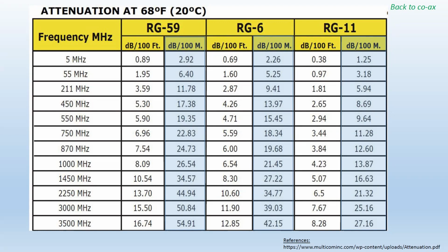Now, sometimes you're going to be dealing with oscilloscopes, and maybe in some labs further down the road in your education, you're going to be asked to raise the voltage by 6 decibels. If you raise the voltage by 6 decibels, you're doubling the voltage. So there are 2 different numbers. When it comes to power, the magic number is 3. When it comes to voltage, the magic number is 6. If you raise voltage by 6 dBs, you're doubling the voltage, or if you're lowering the voltage by 6 dBs, you're cutting the voltage in half, and so on.